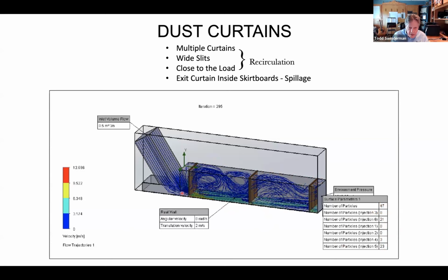In this case, I haven't allowed hardly anything for the material to come up to belt speed. But typically you would probably have a meter or so in there. And what this shows is I put 100 particles of each size in, and by optimally designing this, I'm only exhausting about 50 particles out of 600. So about 18% is being exhausted and the rest is being contained within. The other object is to keep that airspeed down. That's what all these blue lines are in this 0 to 3 meters per second velocity.